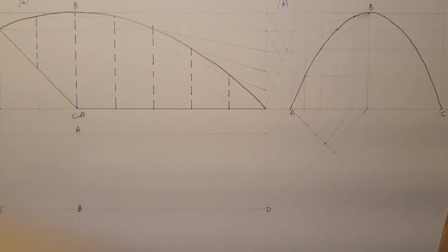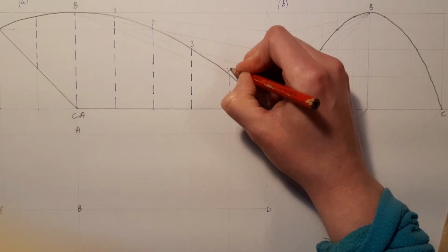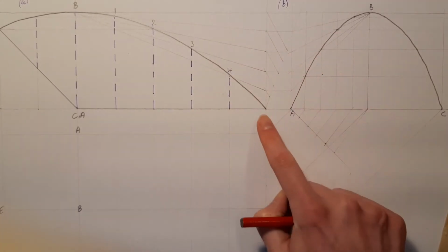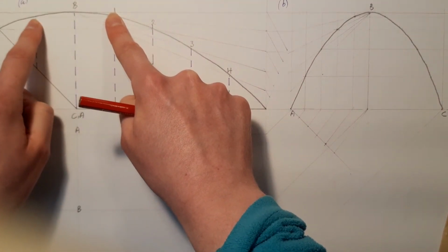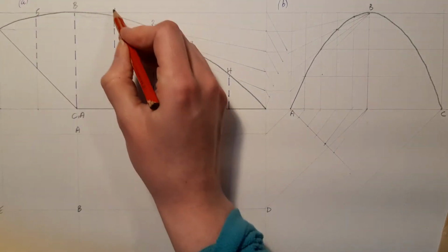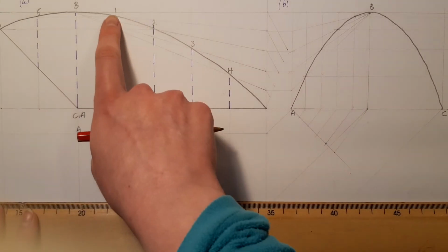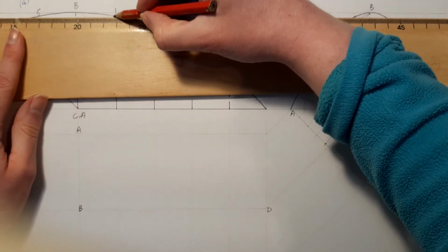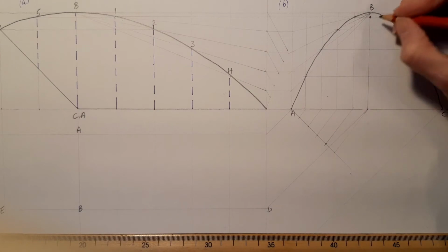Okay, and like I did the last day, I'm going to number these curves. So 1, 2, 3, 4, and the fifth one doesn't really matter because there is no curve, there is no height to it. You can see 1 and 5 are the same height, and 1 and 6 are the same height. Now that we have all of those, we're going to start off with the first curve and find it in my end view. So the height of 1, just transfer it across, is here. Okay, I'm going to call it 1.